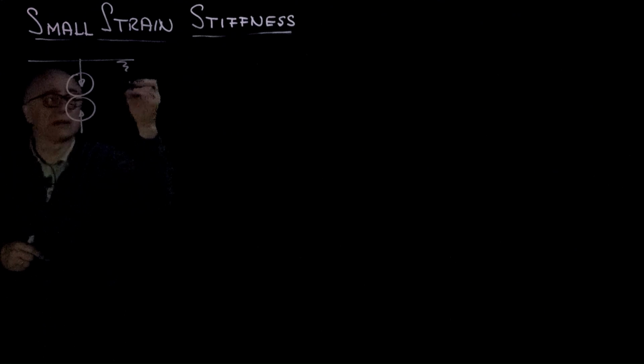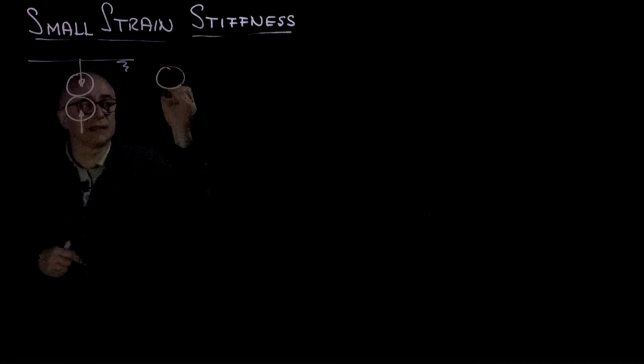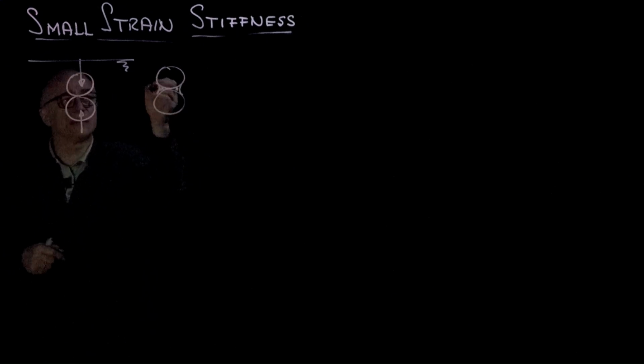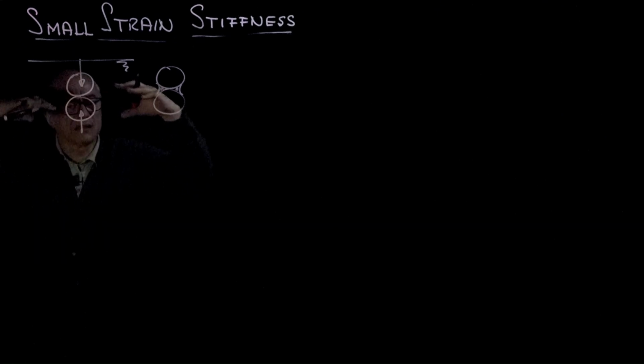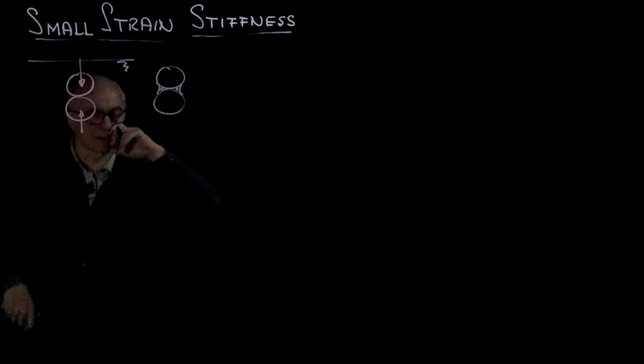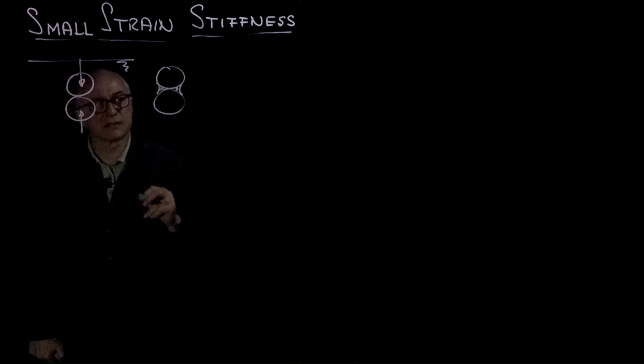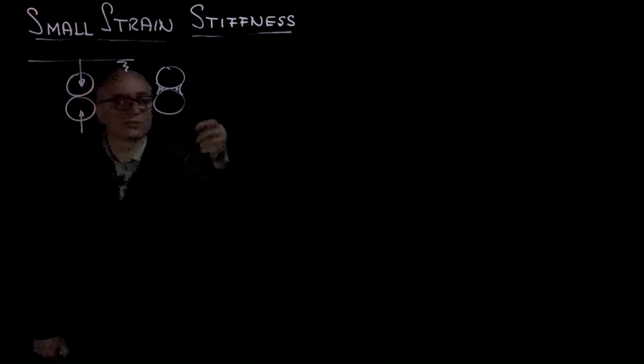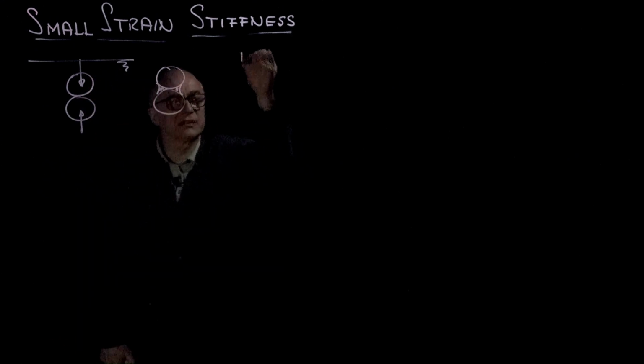What happens when drying begins taking place and there is a meniscus that develops at the contacts? In fact, even before the meniscus develops, there is a surface tension that develops as the water begins to mobilize suction before air entry. This is far into the air entry situation. And so these additional forces are indeed going to increase the stiffness.